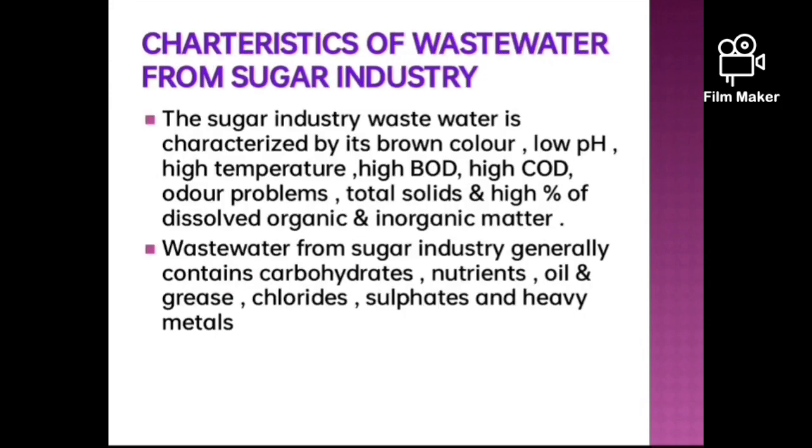Characteristics of wastewater from sugar industry. The sugar industry wastewater is characterized by its brown color, low pH, high temperature, high BOD, high COD, odor problems, total solids and high percentage of dissolved organic and inorganic matter.